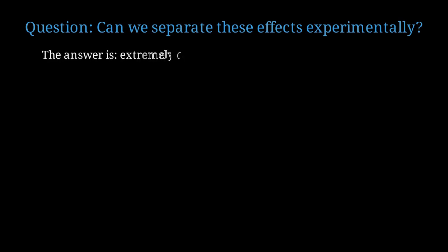Here is a critical question. Can we separate these mechanisms experimentally? Can we design an experiment that isolates ACEO from electrothermal from induced charge effects? The answer is extremely difficult. All three mechanisms respond to the same applied field. They have different frequency dependencies, but their ranges overlap. They have different scaling with conductivity, but changing conductivity affects multiple mechanisms simultaneously.